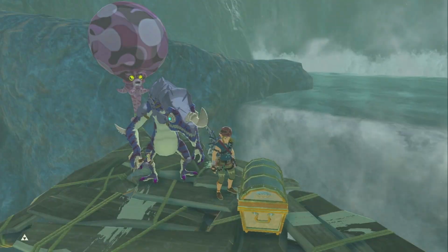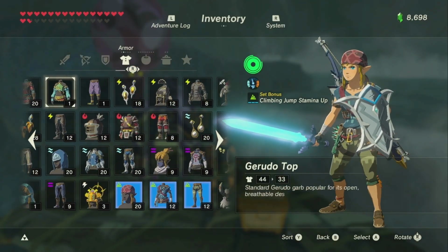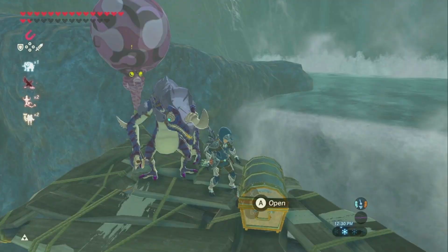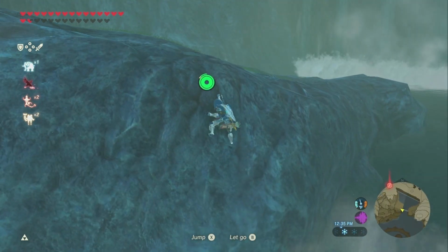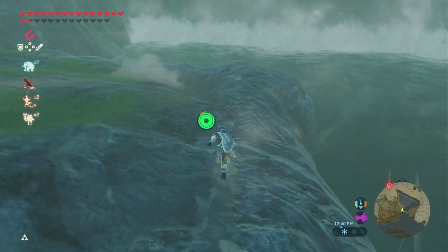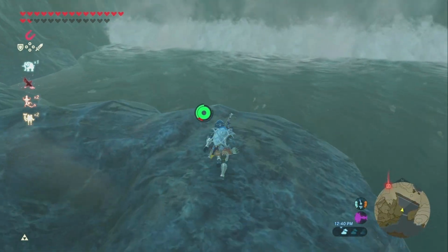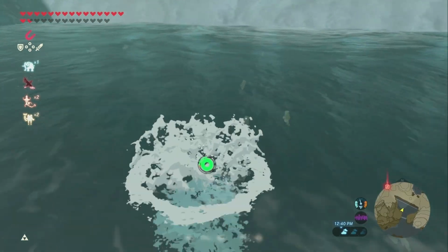Because of slow recovery rates, electrical hot water heaters are typically not used. General rules: output should be 10 to 20 times more than the heat loss of the building. Storage tank capacity should be 30 gallons plus 10 gallons per bedroom.